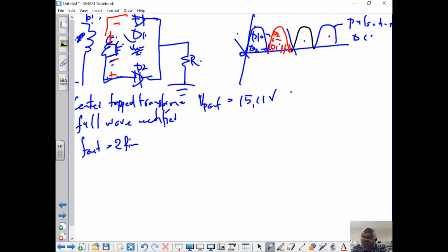Again, this voltage in here, guys, it would be V peak secondary, or V peak out, or V peak rectified, divided by 2 minus how much? 0.7. Very, very important for you to know the peak from there to there. You just subtract one diode and you are able to know what my V peak out is. Are we together, guys? I hope and believe that you are following me.